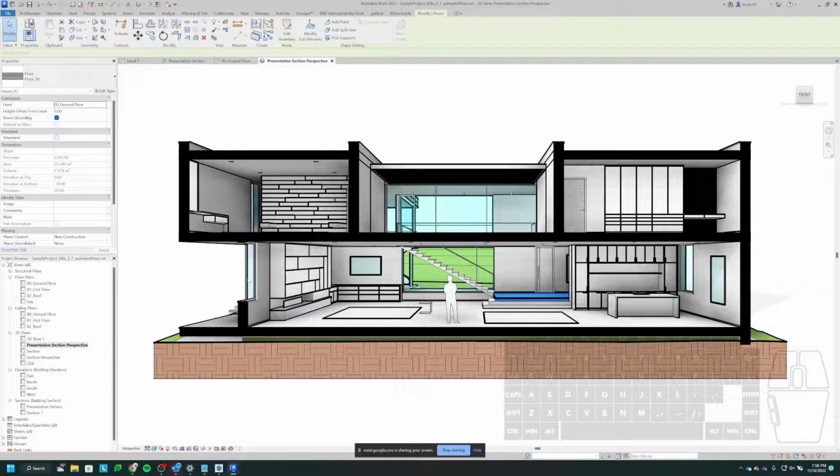Now, like I was saying, the problem with painting materials, I talked about it a little bit last week. But if I were to paint a material on this wall, for example, and I tied a hatch pattern to that paint material, I'm not 100% sure, but I'm 99% sure that whatever is painted onto the surface will override any of these settings that we're doing here.